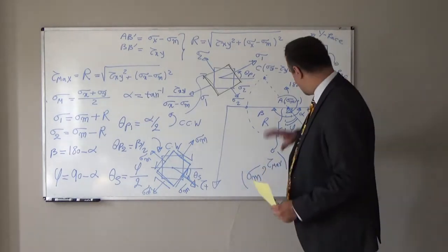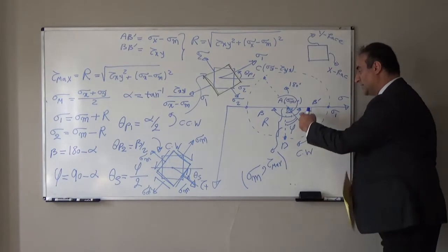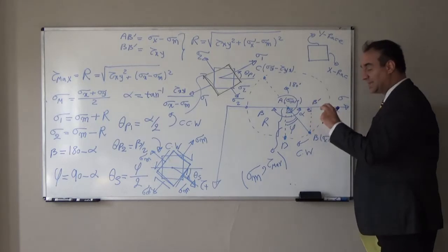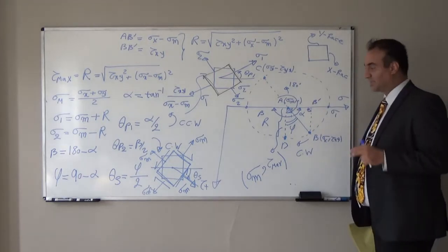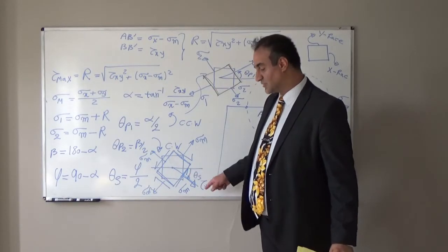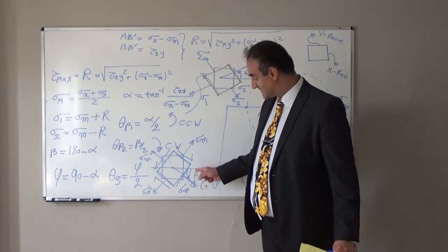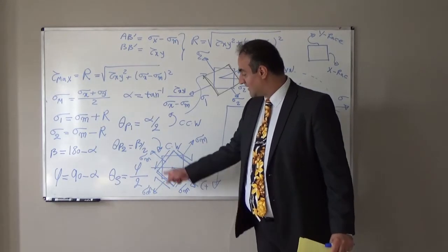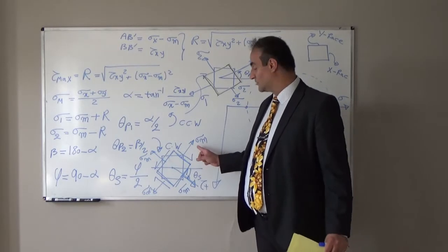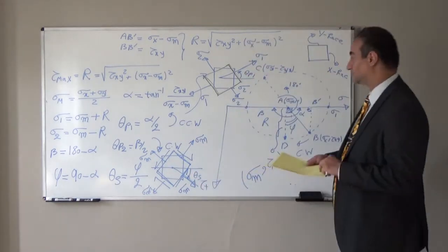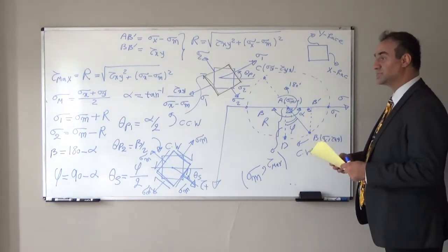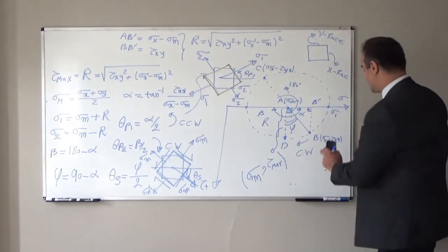So if we rotate this radius phi on the Mohr circle, in the real element we should move half of that, so phi over 2. The x phase will be towards the maximum shear stress, and the normal stress on all faces will be equal, and that is equal to the mean stress. This is the way we will draw the Mohr circle. Let's look at one numerical example.